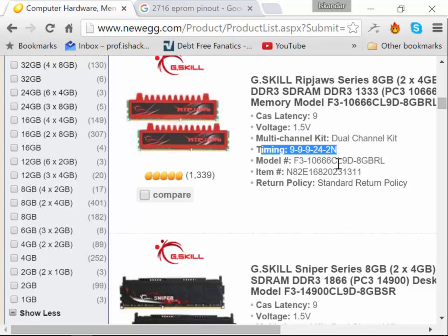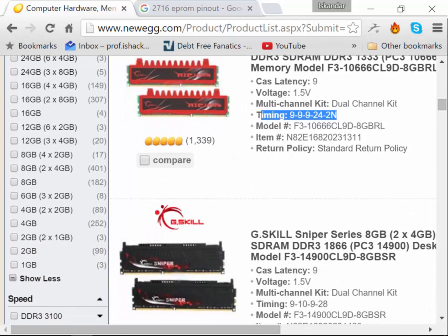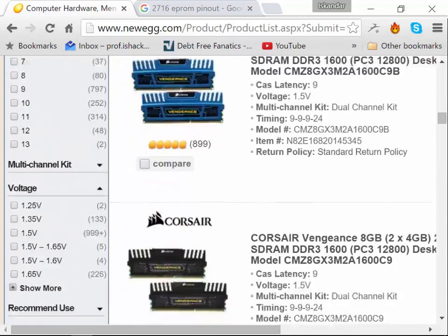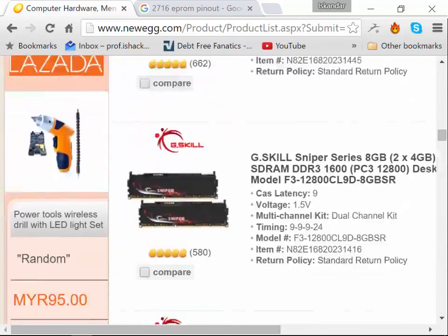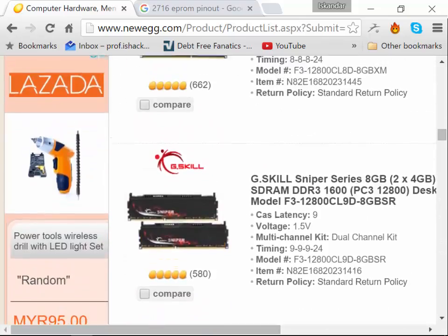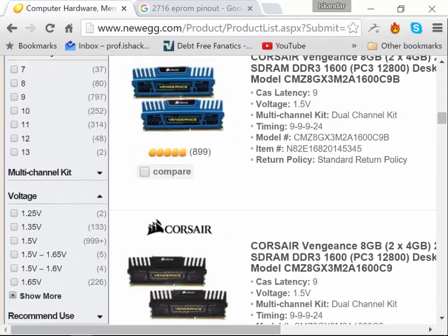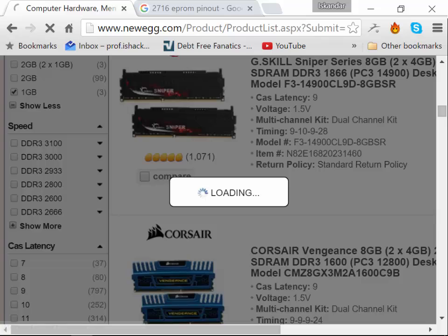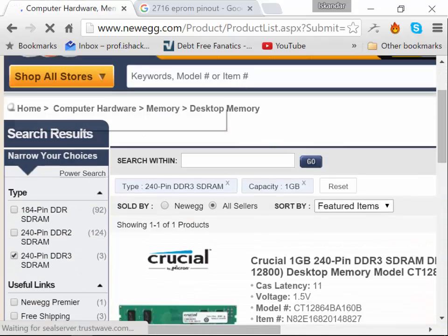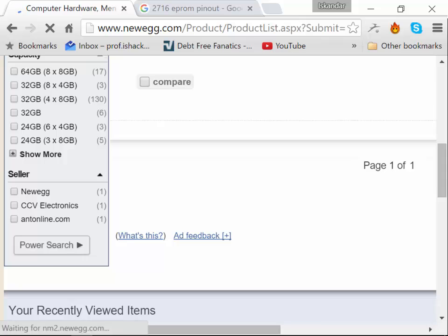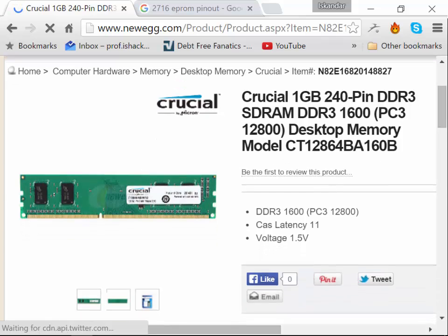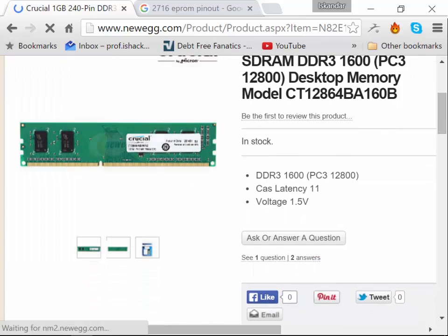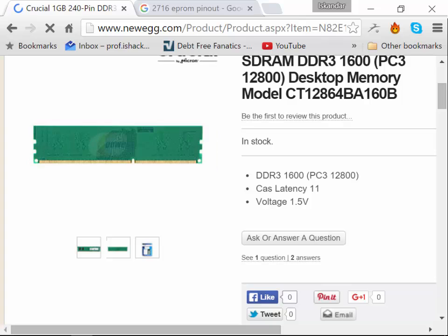Then the last type of memory that I'm going to talk about tonight is dynamic RAM. It uses a capacitor to store the information. But because it's using a capacitor, we have to constantly read it and rewrite to it again. We have to go through a refresh cycle, because it loses its charge. While it's being refreshed, you can't access it. Every so often we have to go through it and rewrite to the RAM, and that takes up time.